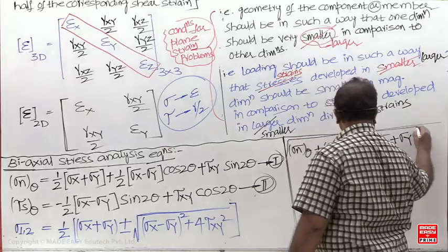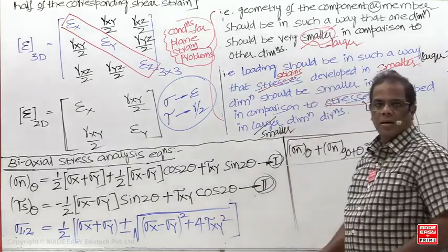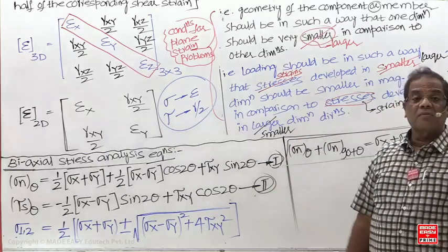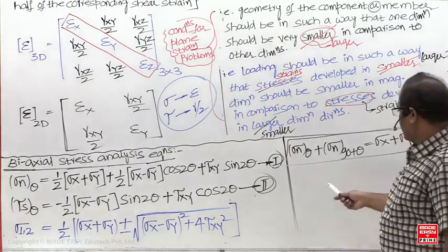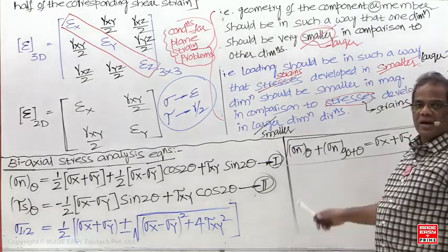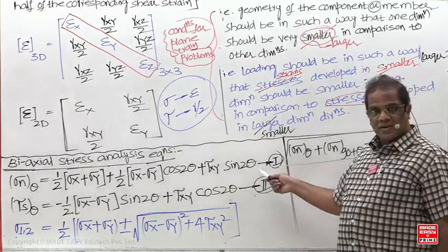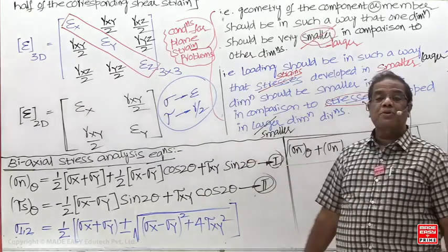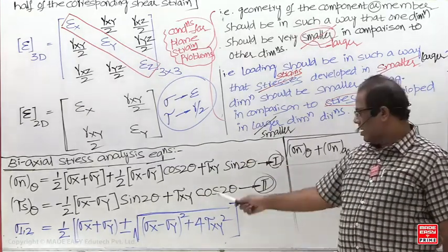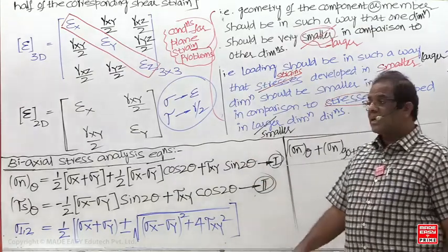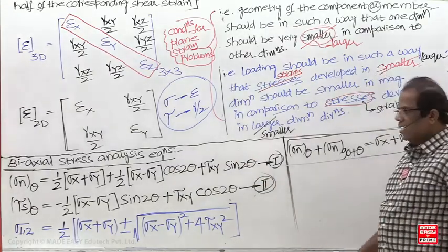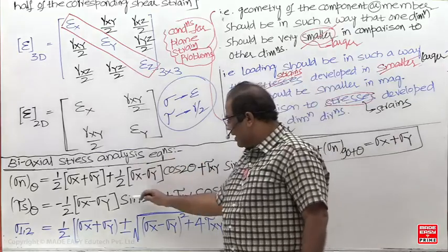This is very important. You studied it yesterday. Complementary normal stresses are what? Maybe equal, maybe unequal, maybe like or maybe unlike. Somebody will ask how you got this relation. What is the answer? In equation 1, in place of theta, substitute 90 plus theta. Then this term overall will become a minus.